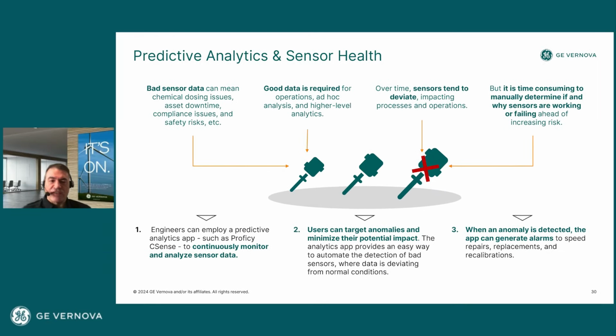Like I mentioned, things like flatlining, out of range values, things that are deviating from the norm more than usual. A lot of the tools here really will help you. It'll give you an early warning. It may or may not be an issue, but if it does detect the anomaly, you can investigate the issue, and maybe it is a bad sensor that needs replacing or cleaning.